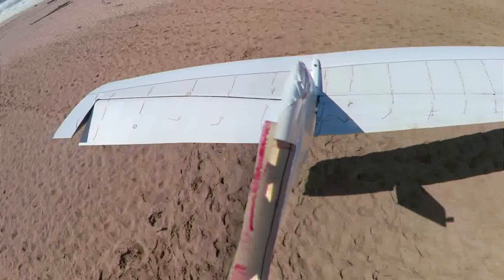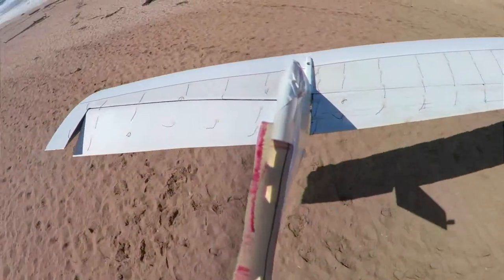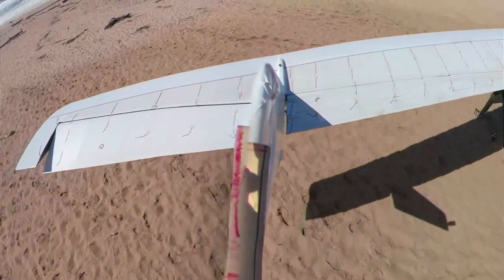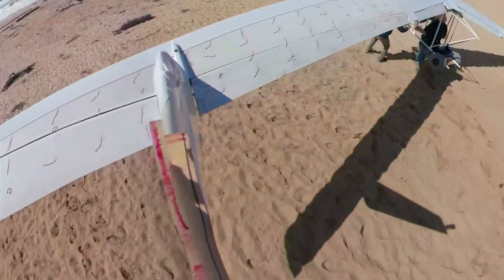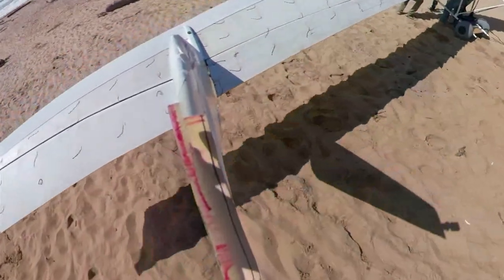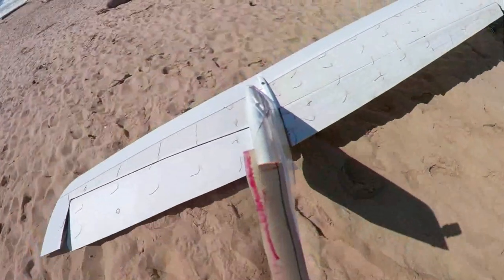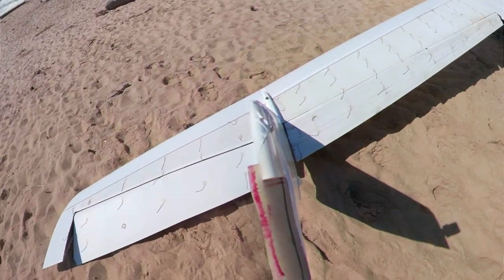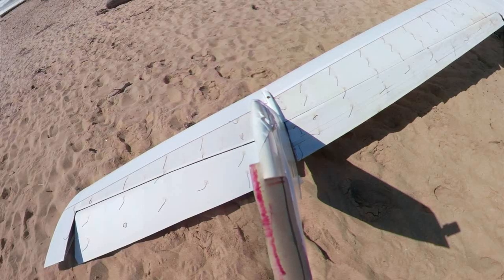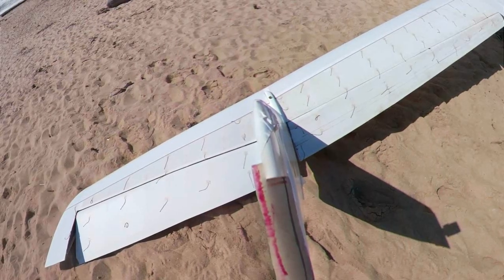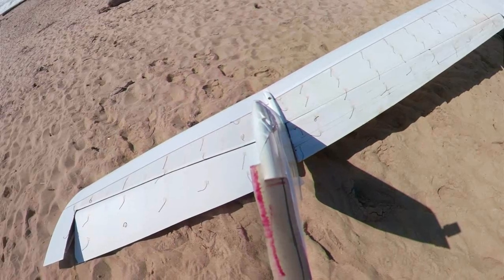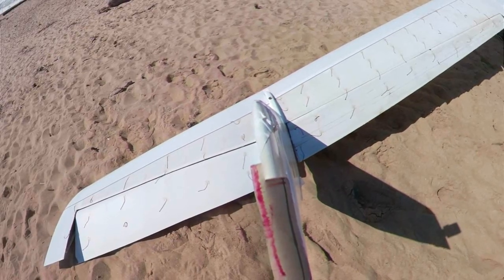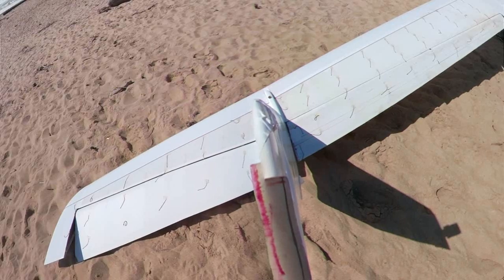So here I'm doing a little run, and I'm fiddling around with the pitch here. And, oh, there you can see me struggling. And there at the end of that run, you saw where the wing came back and it started yawing hard to the left, even though I'm commanding a right turn. I got that down elevon in there to command the right turn, but the wing is yawed left, and very unpleasant, not what we want.